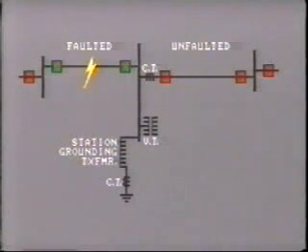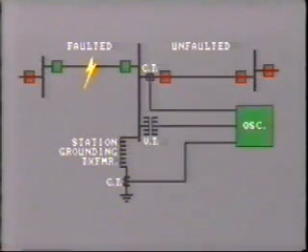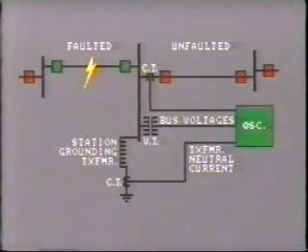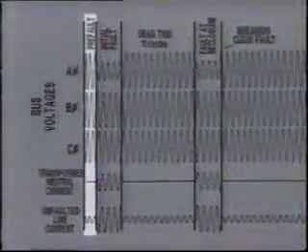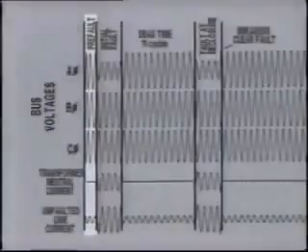In practice, this happens quite frequently when the line does not stay de-energized long enough for a temporary fault to clear on its own. In this example, the oscillograph has captured the substation bus voltages in all three phases, the transformer neutral current and line current for one of the transmission lines. The oscillograph system in use here can record 3 cycles of pre-fault data.